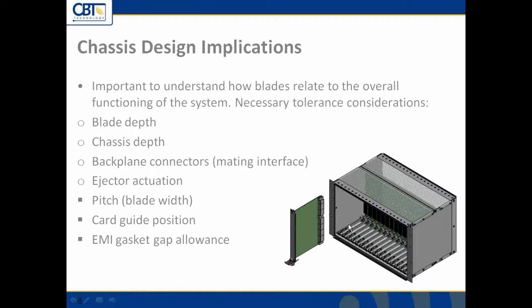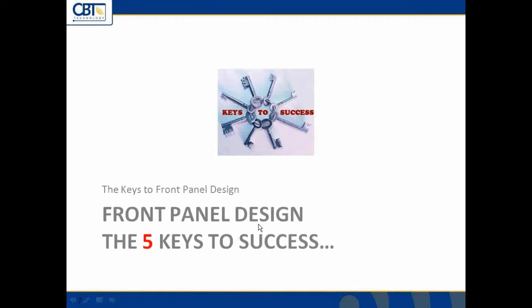And of course that relates very closely to not just the backplane connectors, but the position of the card guides themselves. And then as we'll talk a little bit about as we go forward, the importance to maintain a certain gap between each one of those front panels to allow the EMI to work properly and have the right distance so that you have shielding effectiveness there as well.